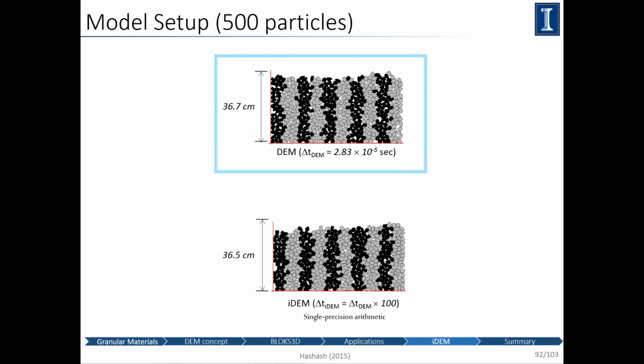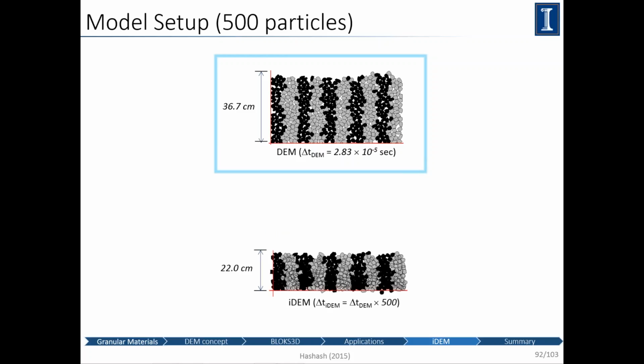You can see it's actually going smaller because if you move too big of a time step, you may end up missing some of the collision. So what will control the time step is the distance between particles. Otherwise, you'll physically have one particle go past another. So that's the limitation, it's physical. It's no longer numerical, and that's very important for us.